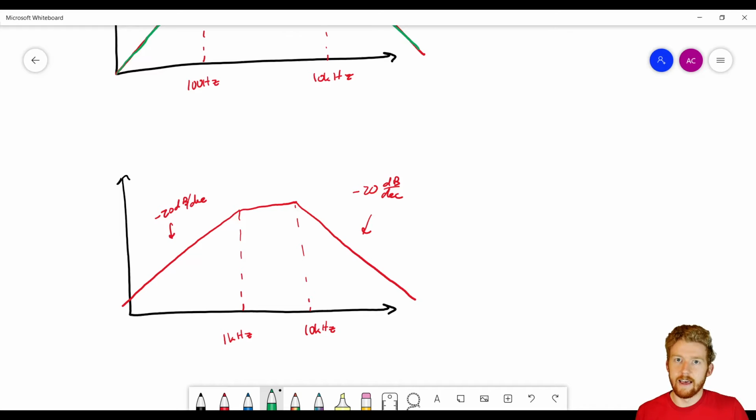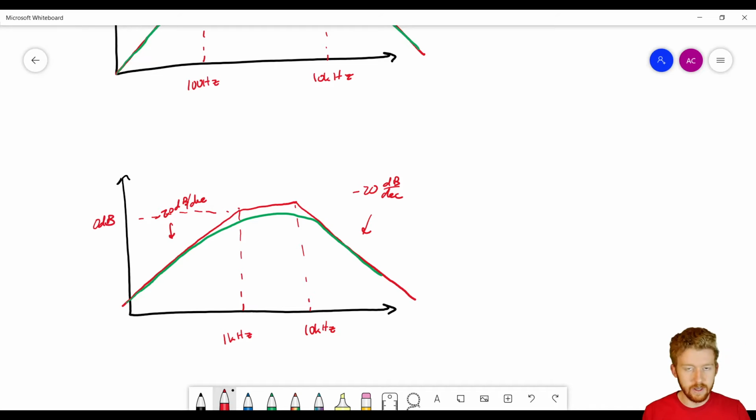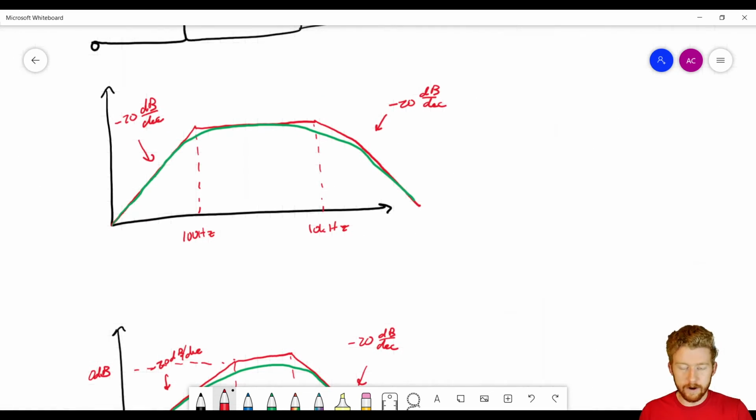But what you find is that whenever you actually simulate this circuit, you get something more or less like this. So you have a very curvy looking line, and it doesn't even quite hit 0 dB. We're expecting in our passband that we're going to have 0 dB. Whenever those two cutoff frequencies are far enough away, up here, even our realistic response is pretty close to 0 dB.